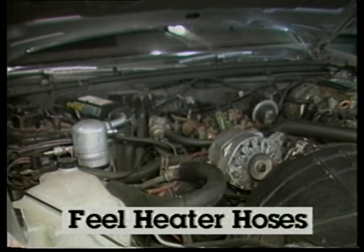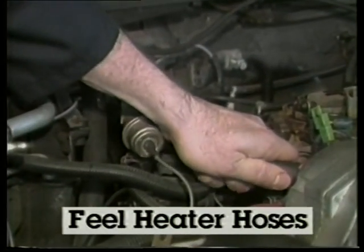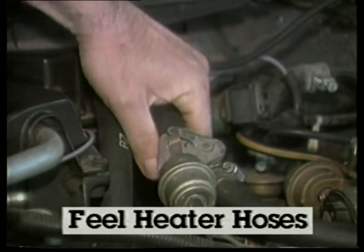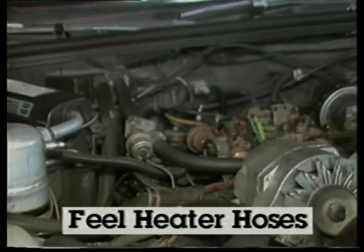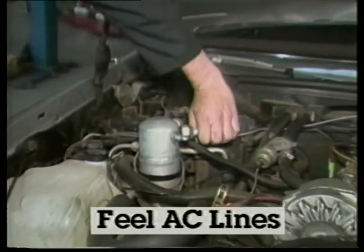An excellent way to analyze heating and air conditioning systems is to check line temperatures. With the heater on, the temperature of the heater hoses on both sides of the heater core and control valve should be about the same. If hose temperatures change, the heater core may be plugged or the heater valve may not be opening.